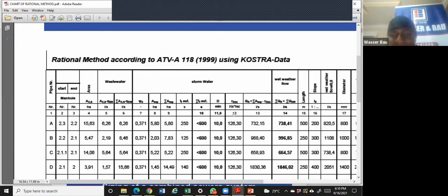After that, you go to your IDF, your rain data, and call out the rain intensity, which is already in liters per second per hectare. You convert it, that millimeter per hour, you convert it, depending on the unit you are working with. This is the value. So if you multiply the rain intensity with the summed impervious area, you will now get your Q. So we multiply this by this, you get your Q. So this is now the end of stormwater here.